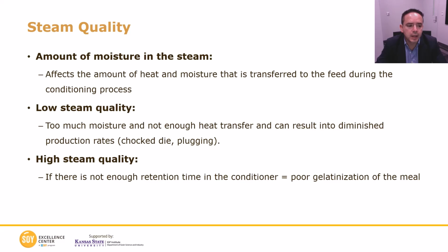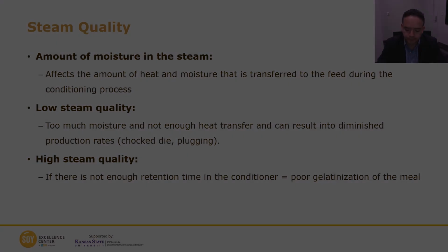If you have high steam quality, this means that there is not enough water in the steam. And if there is not enough time in the conditioner, then there is going to be poor gelatinization of the starch in the meal, and poor denaturation of the proteins. So you need to monitor steam quality. And if I recall correctly, good steam quality is going to contain about 97% steam and 3% water.